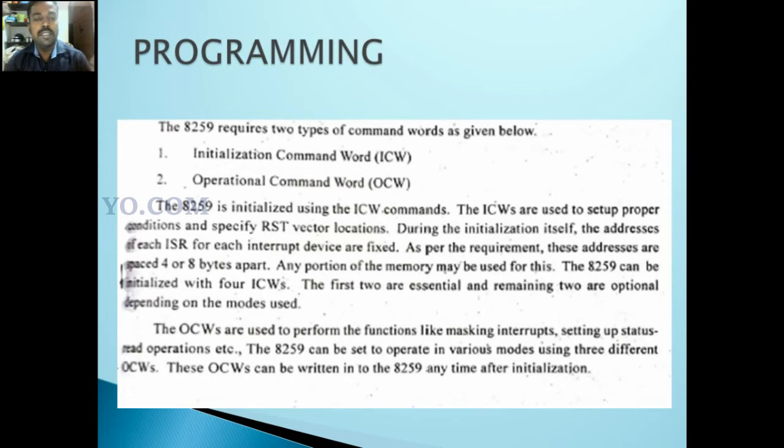So actually we have 4 initialization commands. The first one is initialization command word 1. This is an 8-bit command word. See the individual bits. The first bit is IC4. If this bit is 1, then ICW4 is needed. If it is 0, it means ICW4 is not needed. ICW4 means the initialization command word 4.